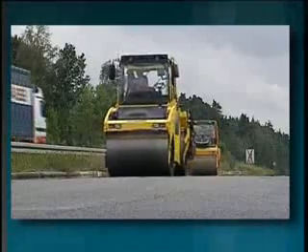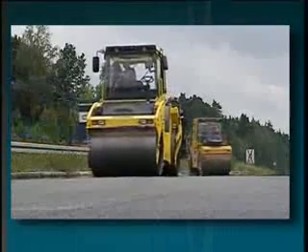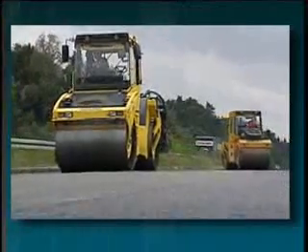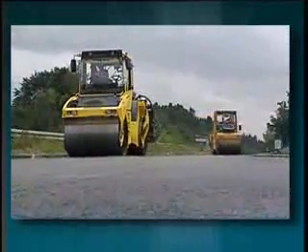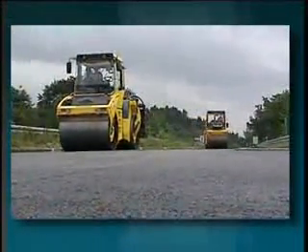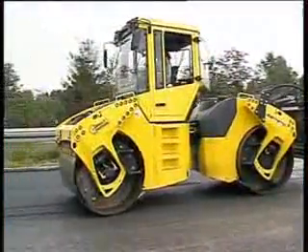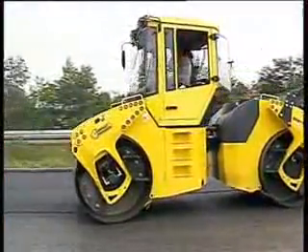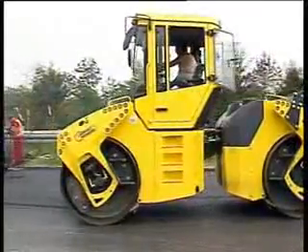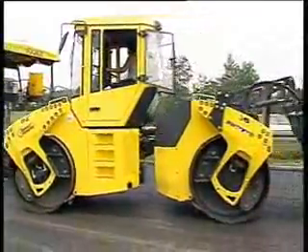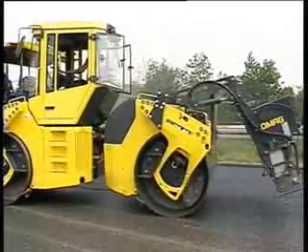To achieve all this, modern rollers must have high compaction performance and an intelligent control system to be able to exploit this potential effectively. The compaction performance of a roller increases with higher amplitude and static linear load. However, with the Asphalt Manager, the efficiency and quality of compaction is optimized by automatic control.